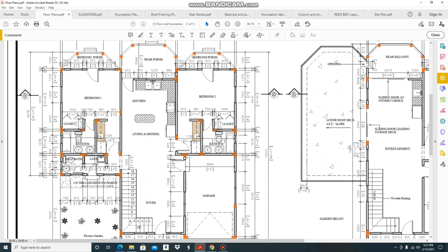And also the stiffener column is placed strategically at these locations to prevent the building from moving when you have differential settlements in your soil. So the stiffener column will limit the amount of cracks, structural or flexural cracks, that you will get in your building when you have shear movement or shear forces or differential settlements in your soil. So it is critically important that you pay keen attention, as a builder or contractor, to the location and placement of your stiffeners.